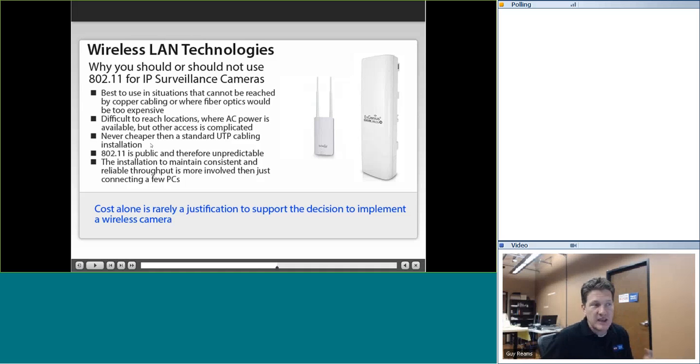And the same thing goes: somebody can decide to install some microwave dish that competes with the wireless signal that you're using, and boom, your camera no longer works. So be very mindful when you decide to go after a deployment of many cameras in wireless, especially outdoors, and even indoors, especially in a multi-resident facility or in a building that has shared tenant access. Be careful, because access points spring up like crazy.